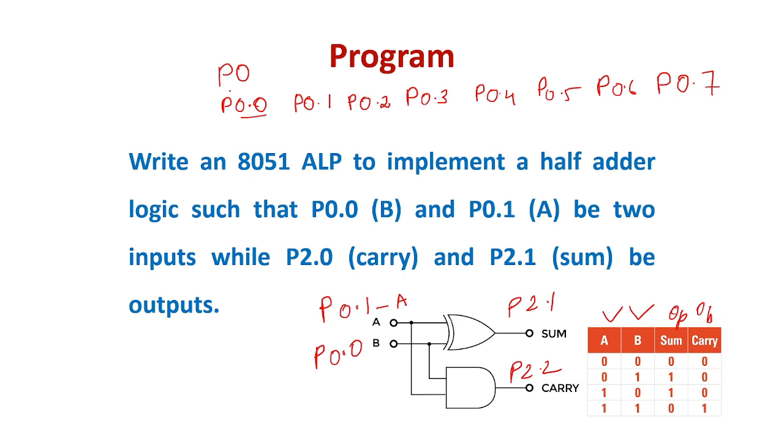Repeating again, there is no bit oriented XOR instruction in the 8051 microcontroller, so you need to use a byte oriented instruction, which operates at the bit level on the entire 8 bits. That is important to remember before you start to write the program.